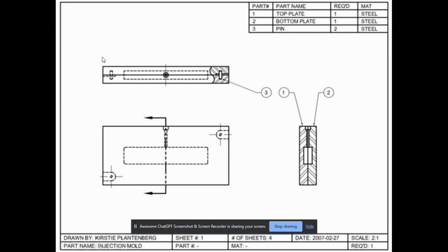We have this particular drawing where we are supposed to produce the section view. We have the cutting plane indicated there, and like the rules in section view, we draw the sectional view adjacent to where the cutting plane is, depending on the type of projection that we are having. If it's a first angle projection, we know where to place it. If it's a third angle projection, we know where to place it. I still recommend the slides that we have in this particular class. Get the slides on section views and also the videos on section views, and you'll be fine.